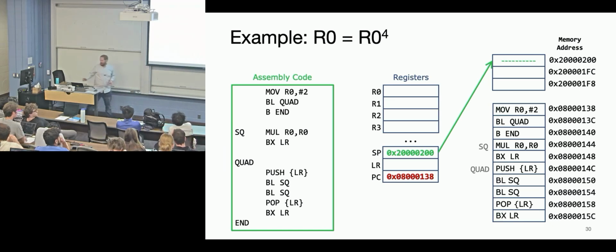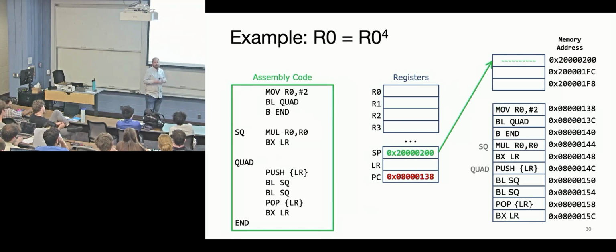So that address the stack pointer has in that register right now, is that the first spot where you can throw data in, or does it need to change first? It changes first. That is where valid data is, somebody else's valid data. The next location is not necessarily unallocated, but it's not part of what's been kept track of, if that makes sense.